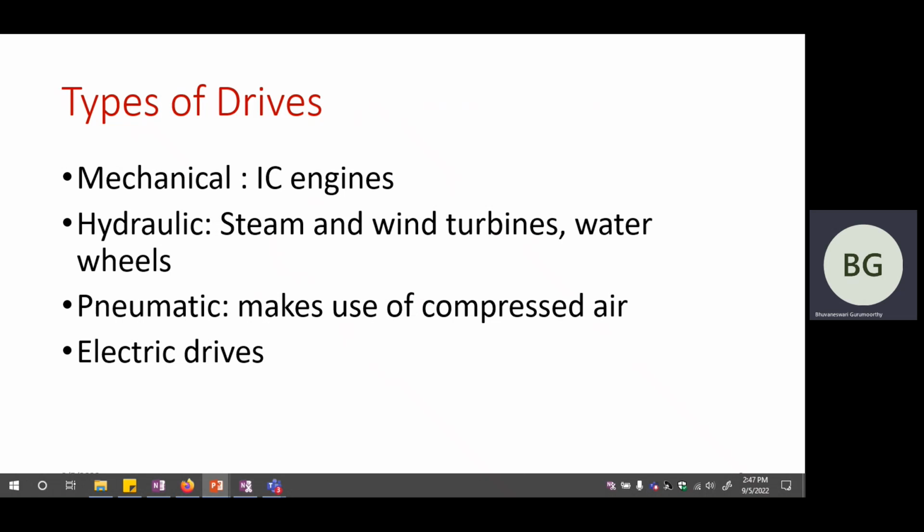So that is the reason why we use a lot of gaskets and rubber linings and things like that. So if there is even a slight leakage, there could be mishap. The entire mechanism could become very messy. So that is the reason why, although hydraulic mechanisms are available at extremely large ratings, the mess associated with that, the dangers associated with hydraulic drives, these are some of the problems. So if they could be replaced by electric drives, that would be wonderful.